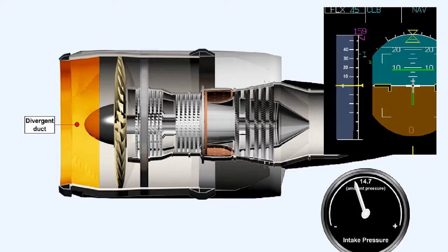This is because the engine compressor is increasing the velocity of the airflow through the intake. As the aircraft begins to move, the pressure within the inlet starts to rise. The ram pressure recovery point is usually reached at between Mach 0.1 to Mach 0.2.